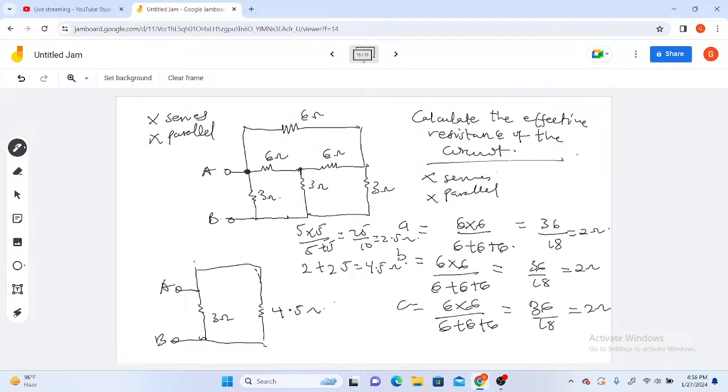So this is just a straight branch, and their combination here is 4.5 ohm. So this is where I stopped and I was explaining that 3 ohm and the 4.5 ohm, never think they are in series, like the same current to flow through them. No, please. The reason is there is a source here coming, and this here becomes a node. This also coming from the source, this here becomes a node. So please, this connection here, because of the presence of these two nodes, make it parallel, right? So once they are parallel, if you really want to see this well, we can redraw it this way. You can see that these parts are not necessary, so you just clean this side.